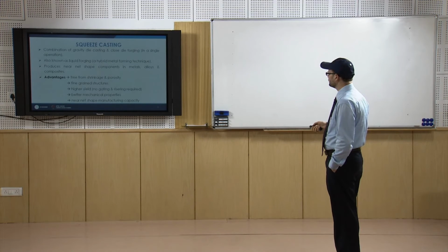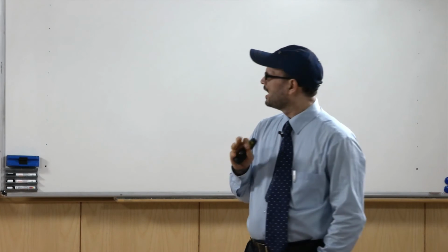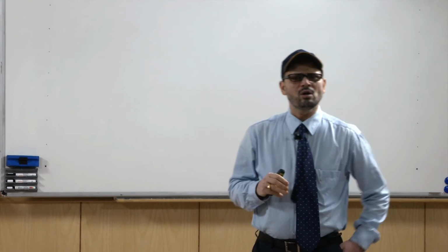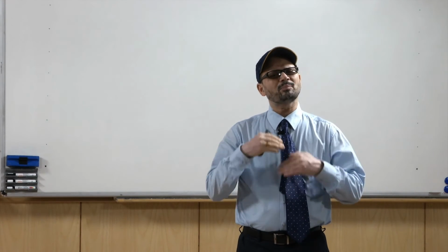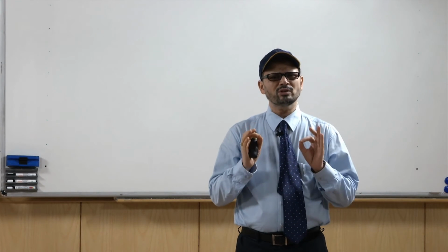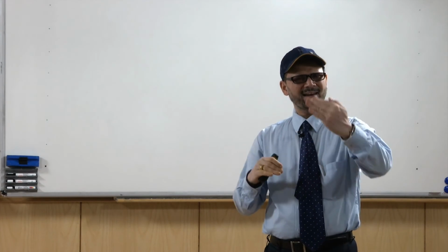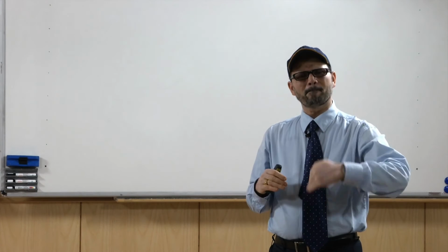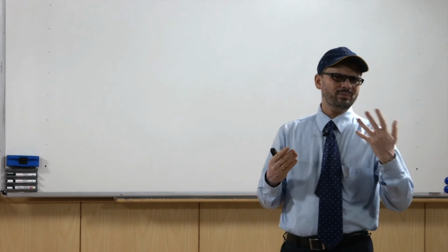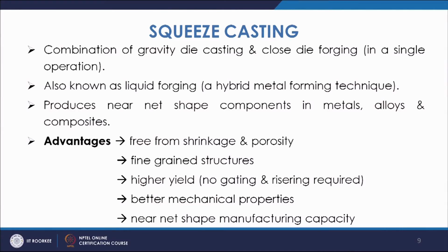Better mechanical properties, as the material will have fine grained structure and also it will be free from shrinkage and porosities. So, once you have fine grained structure, the properties will be better. The fine grained structures produce good tensile strength, based on certain formulas which tell that because of the fine grains your strength of the material is higher. One of the formulas is the Hall-Petch relation. So, because of that you get better mechanical properties.